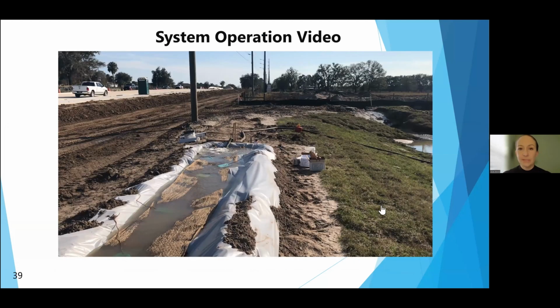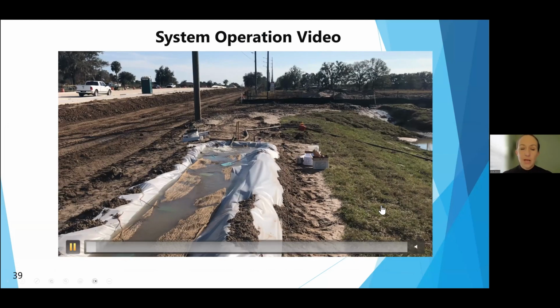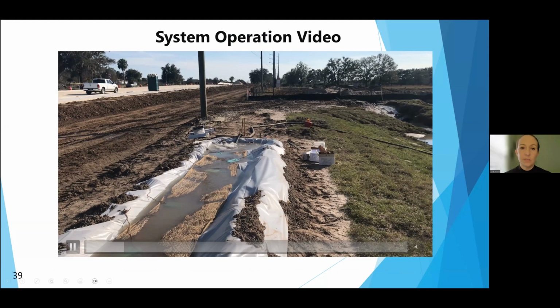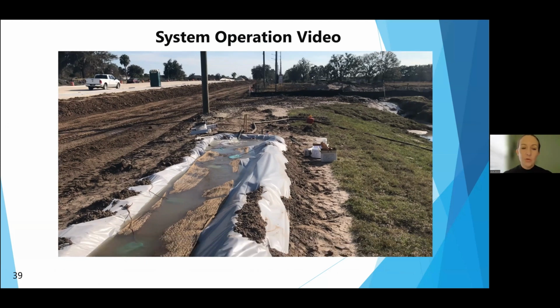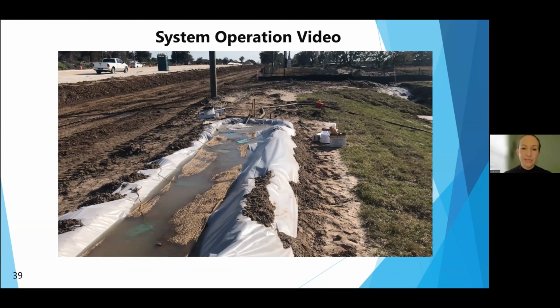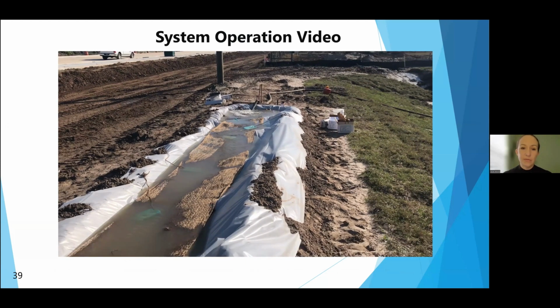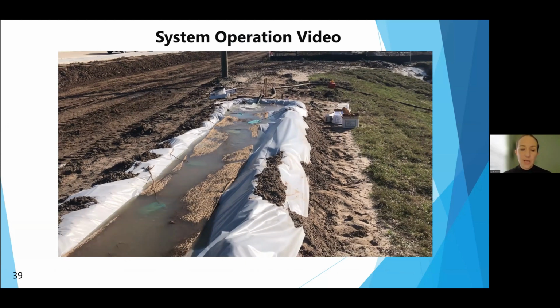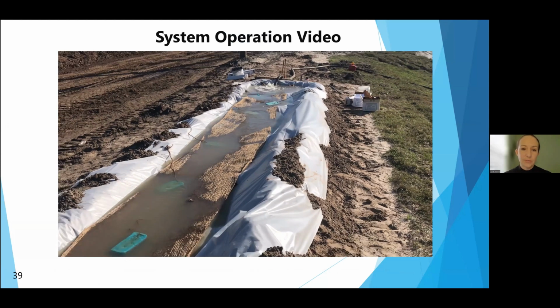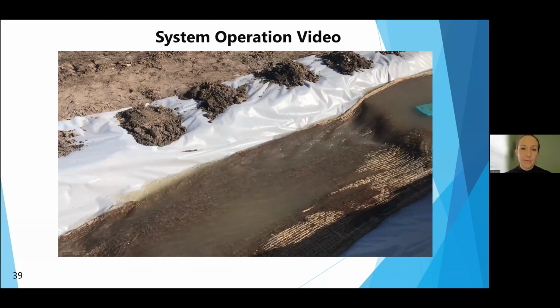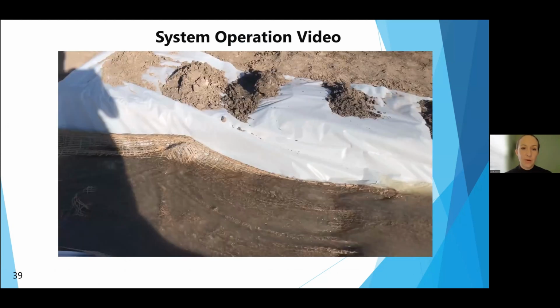Okay, so again, our basic dewatering channel, we're pumping the water out. It's moving over and around the logs, and as it's going over the logs, they're dissolving. Once that dissolved polymer is in the water, we want that mixing and reaction time to form those flocs. As the water's moving down the channel, that's what's occurring. Once we get to the back end, the jute matting is collecting some of that particulate, and ultimately we're settling the flocculated particles in the basin.